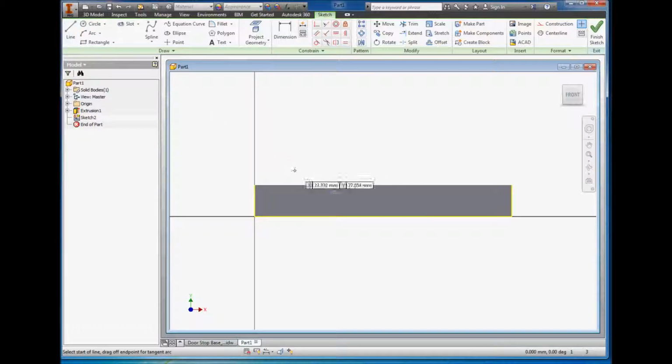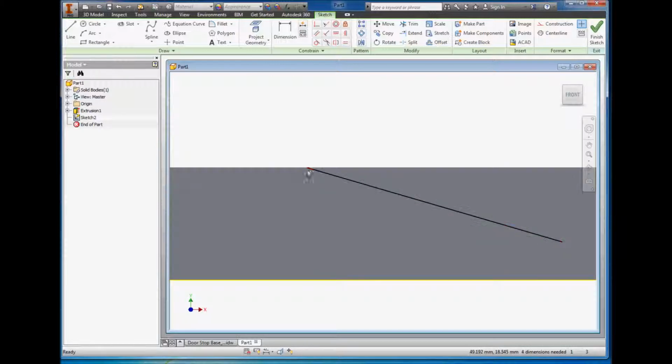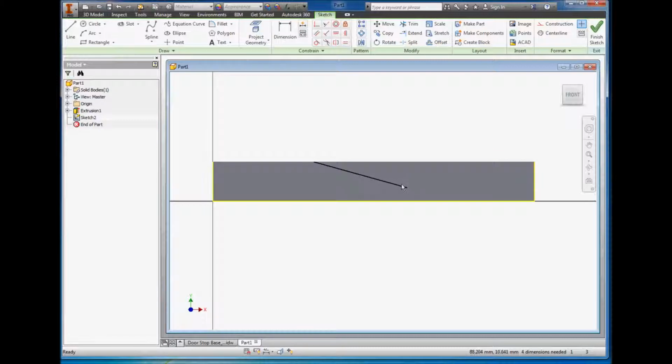And if I wanted to draw a line connected from that point to that point there, let's just say that line there. This point won't snap to anything. There's nothing to snap to because that line doesn't exist. If I zoom in and have a look here, it's got no reference geometry to snap to. So that's why we need that offset line and not to delete them.